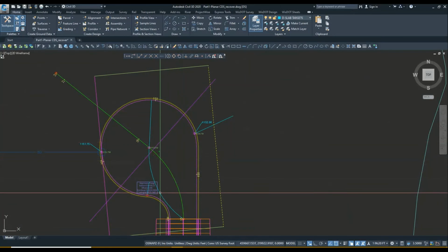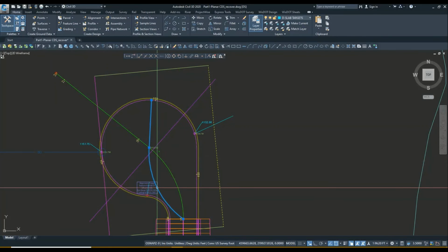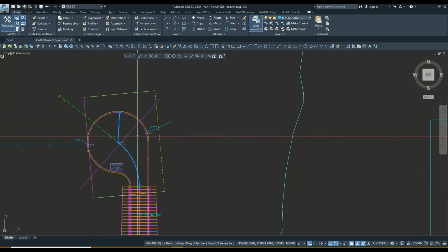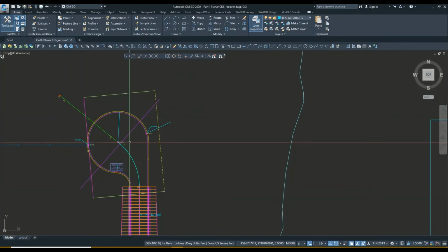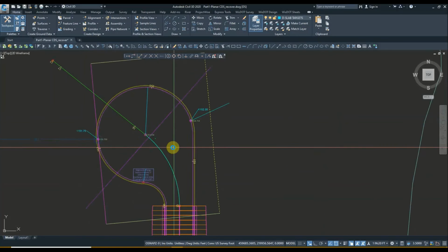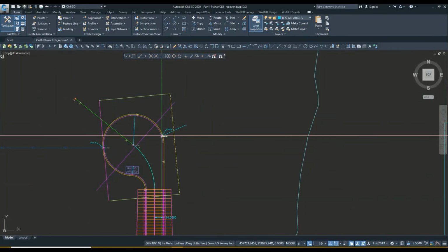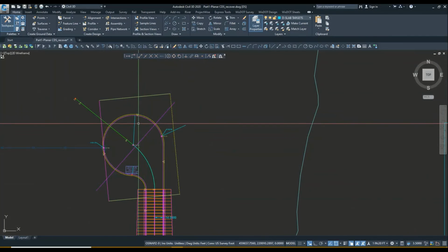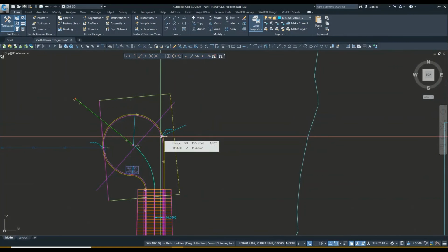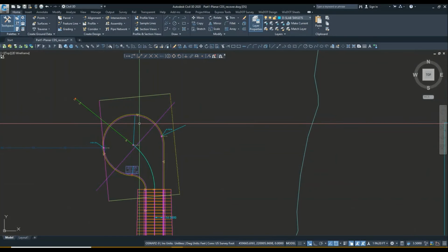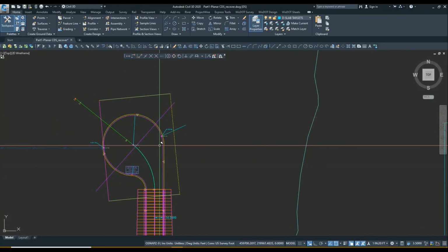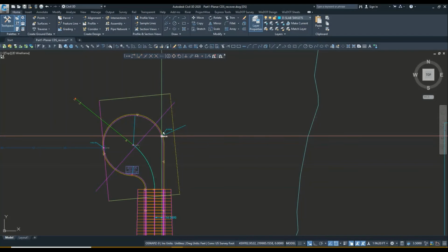So I will do this with a polyline and do that. Okay, so now we know this area wants to drain this way, this area wants to drain this way. And we can't do what we did before, where we just created a perpendicular feature line and created it this way. And the reason is because we want the direction of this setup surface that we'll be creating to go this way. And the thing is that we want it to connect to the ridge line so that it drains always in the direction of this inlet.